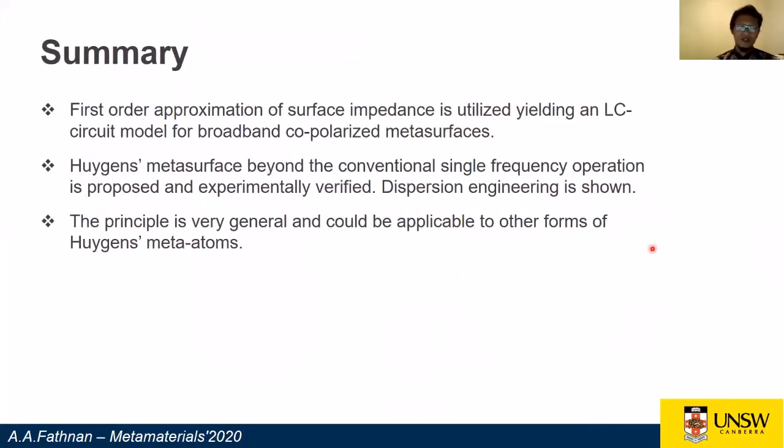So in summary, we show that the first order approximation method of surface impedance can be used to obtain LC requirements for broadband copolarized metasurfaces. And we also show that the Huygens metasurface beyond conventional single frequency operation can be experimentally verified, where we also show that dispersion engineering is possible. And we show that the principle is very general and could be applicable to other forms of Huygens meta-atoms.